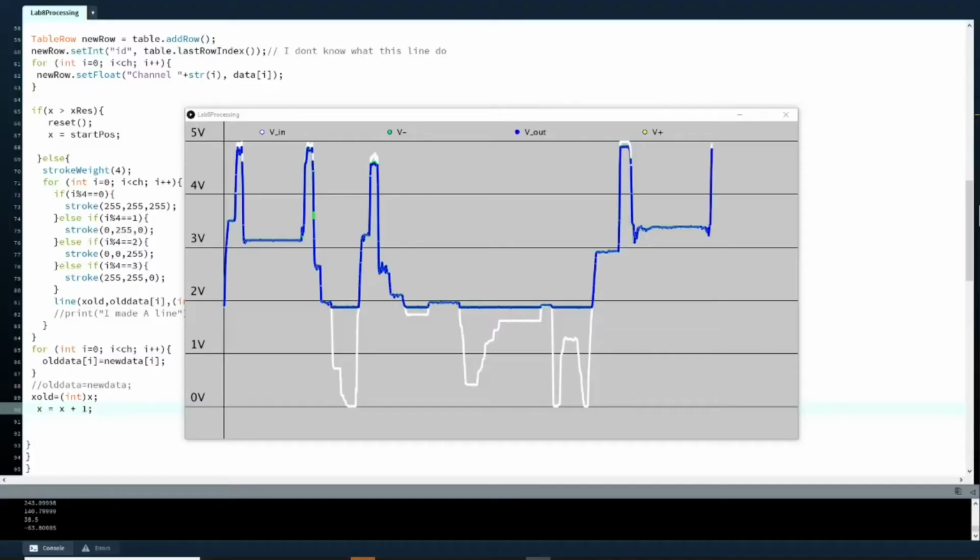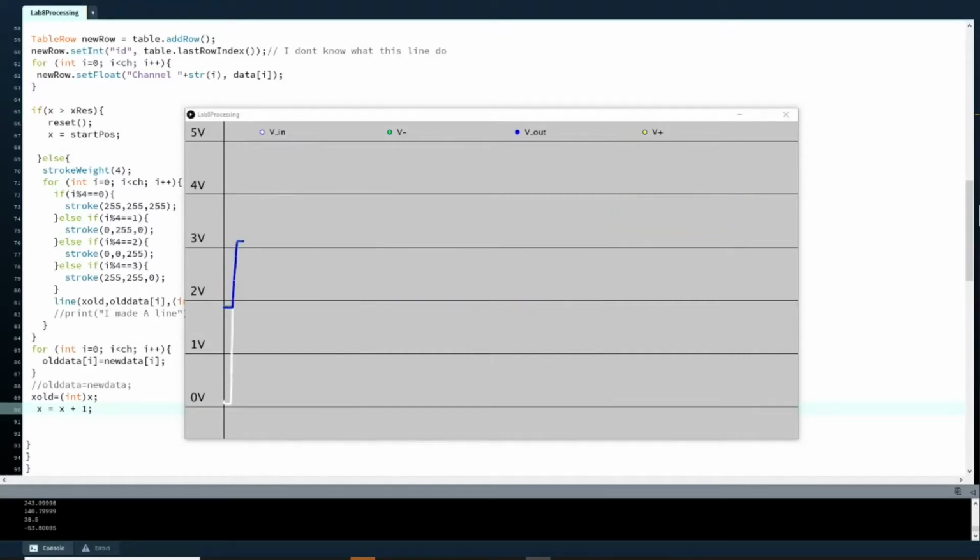Here we can see the response of the unity gain amplifying circuit of the op amp. As you can see, it doesn't provide the proper response when the input voltage is below 2 volts. The reason for that is the data sheet doesn't provide a response under 2 volts. The response is from 2 to about 11.5 volts. Because the VCC for the op amp is only 5 volts, the response for the op amp in its current configuration goes from 2 to 5 volts, as we see here in this circuit.